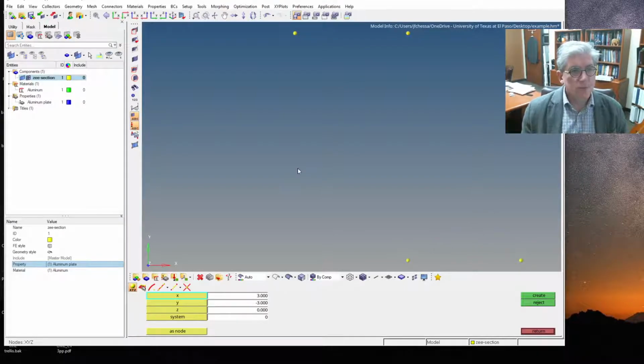So when you scroll, you can use it like mostly, I think it's control with the different mouse buttons. So control with the left mouse button does rotation. Control with the, that's kind of a cool one. Let me zoom out. If you do control with the middle button, you get this little window and you can zoom in on it, okay? There's fit over there. And then the right mouse button is to pan. I think if you just do the middle mouse button, it doesn't do anything, but that's it, right? Okay. So it's control, and that gives you those options, all right?